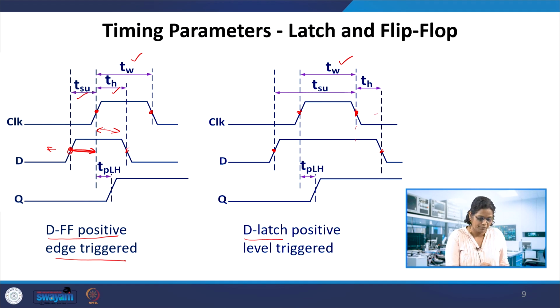So the setup time and hold time give the duration, the window, for which the data is to be stable. Here also TH is shown from this point to this point, the TH for the latch as well as the flip flop.